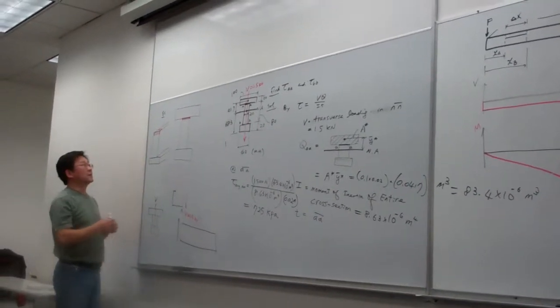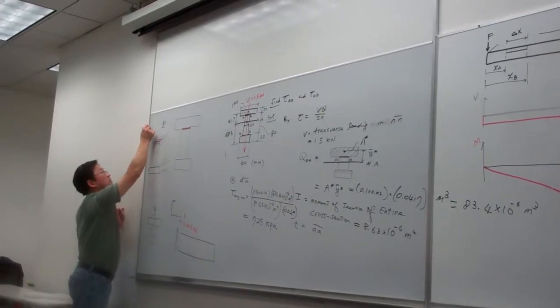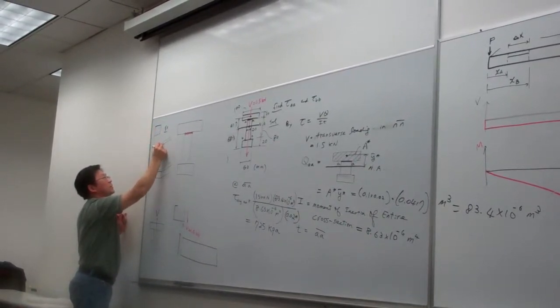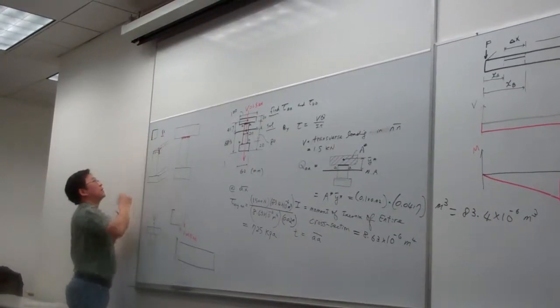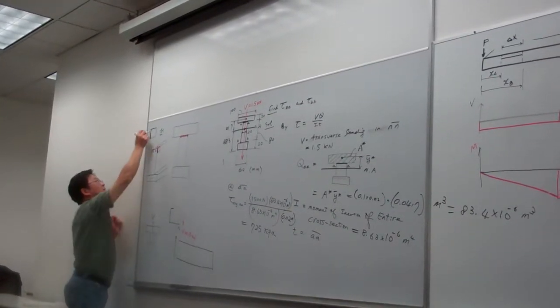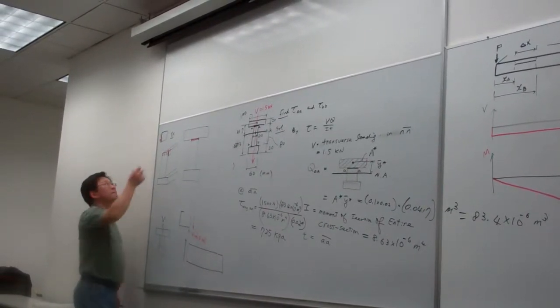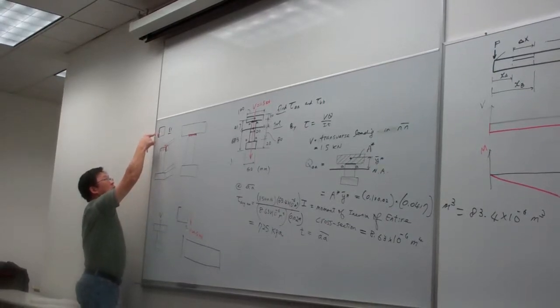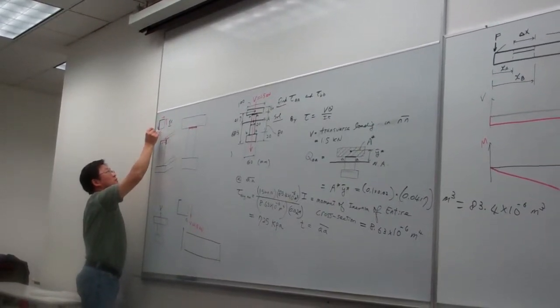Because the concept is this: if you are able to pick this small element, on this small element this edge is here, and that one is the calculated shear stress like this. And then again, using our chapter 1, once we know the shear stress on one side, then on the other three sides we can right away draw the shear stress like this.